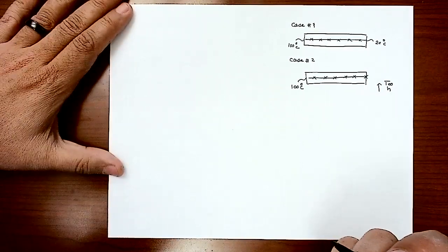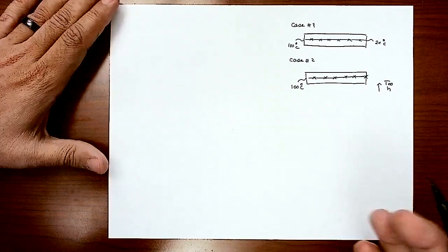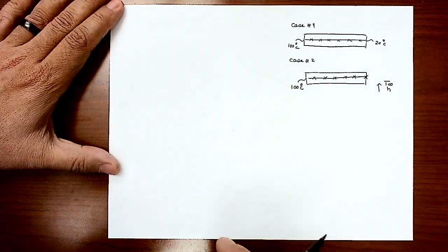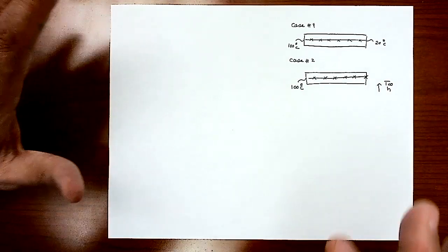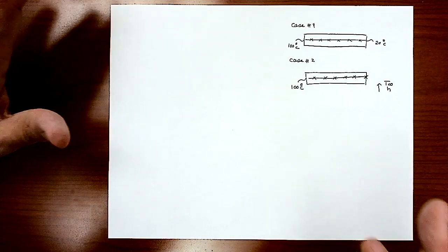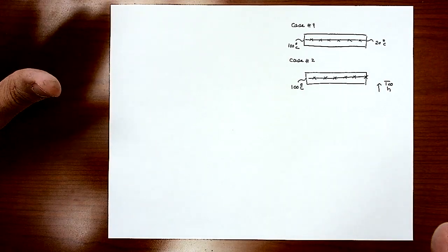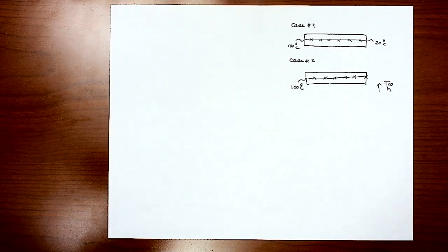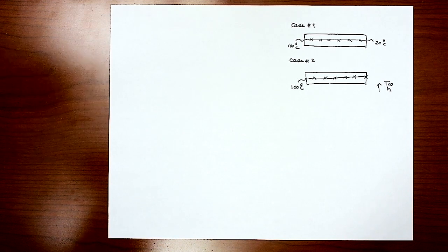I would like to take the example to a little bit higher level. So I'll take example case number two, but what I'm gonna do is add a heat generation to that one-dimension bar. These examples are just to practice how to deal with a problem at the simplest level, but with different boundary conditions. So when we went from Dirichlet boundary condition to mixed boundary condition, I will go with mixed boundary condition, but I will add heat generation to it. And then for the last case, it's gonna be a little bit mixed, where we have one face exposed to convection, heat generation exists, but we will isolate one of the faces.